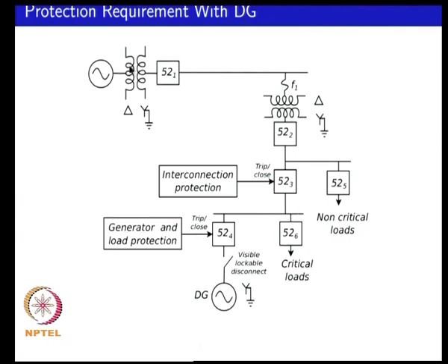So, for example, this is an example where you are connecting DG to a facility and you are coming through your mains, your point of coupling might be just immediately downstream of your transformer, and you have the main breaker coming into the facility. You might say split it off into non-critical loads, which you might be able to shut off in case of failure of or poor power quality on the grid.